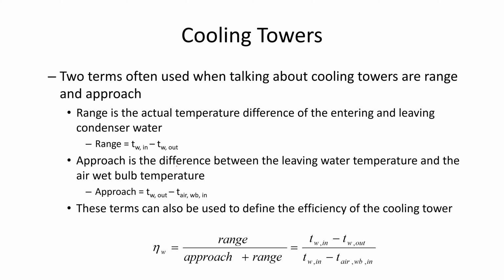Our cooling tower, it'd be great if we could get to 100% efficiency, but the reality is we'll never get there. But we can get close, or we can get down to a certain point, and that's what that measure of approach is. So the smaller your approach, the smaller that value is, the greater efficiency you're getting on that system because you're approaching that wet bulb temperature outdoors.